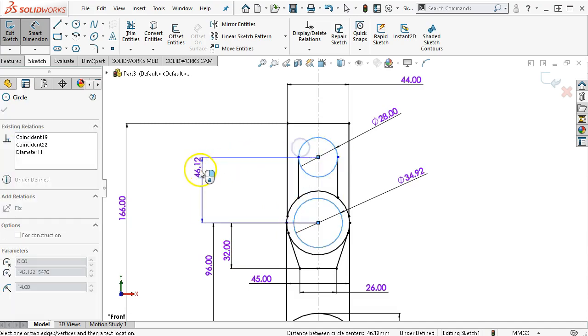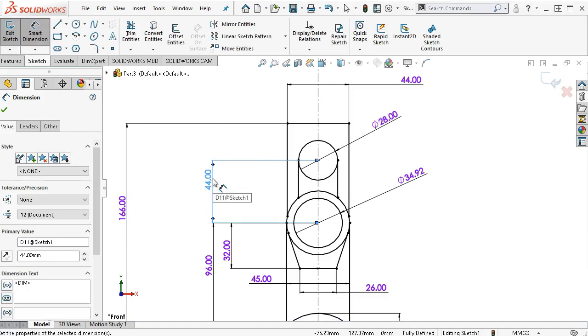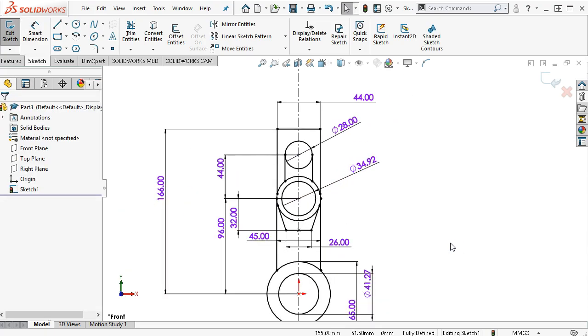So I guess we could go ahead and put the hole wizard item in there, and it'll put in the minor diameter, and we'll not worry about cutting threads and including those in our mass calculation and center of mass. So that gives me a location for it anyway. I think I have enough geometry to go ahead and be dangerous.